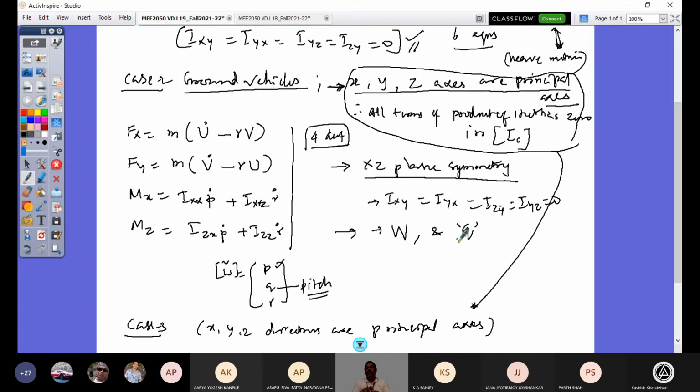My vehicle is not going to go on a road hitting front and back like that. In a steady state, or whenever I go straight or take a 2D motion, when I give a steering input, I don't get my vehicle pitching. The load transfer is not going to be like that unless you go slow over a bump; that time only it is there. Otherwise, at a cruising speed, called the steady state motion of a vehicle, you don't see this Q pronounced. That's why we neglect it.